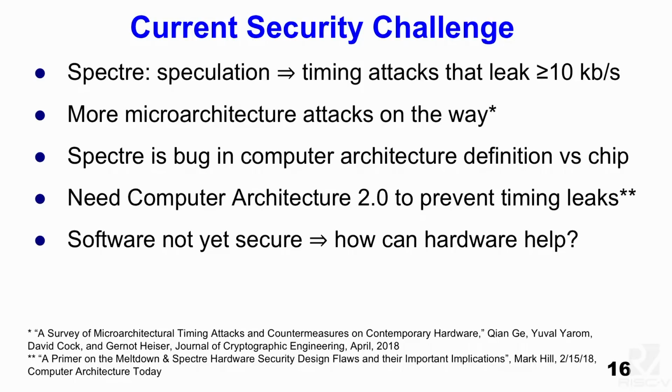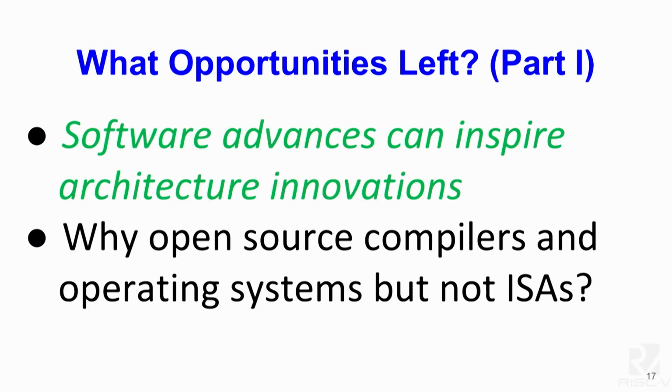All right, so no more Moore's law, and performance isn't getting any better. What else? Security. So the Spectre attack shows that speculation can leak information. Before, timing didn't matter, according to IBM. As long as it's compatible, you didn't care about the timing. Timing can leak information. This is a serious attack on our principles of computer architecture, and it's not going to be easy to fix. So we're going to have to take that on. So that sounds pretty bad. No more Moore's law, performance is over, and the way we build microarchitectures is vulnerable to leaking information. It's not the software that's the problem, it's that the architecture is worse.